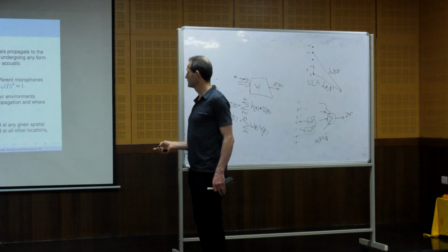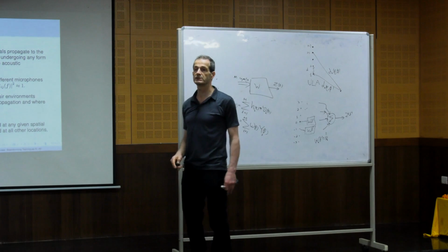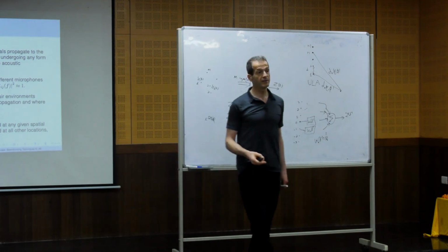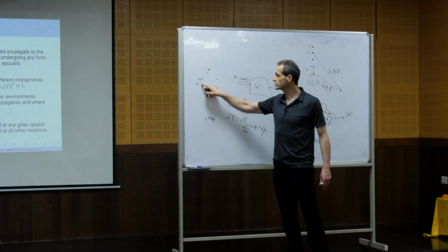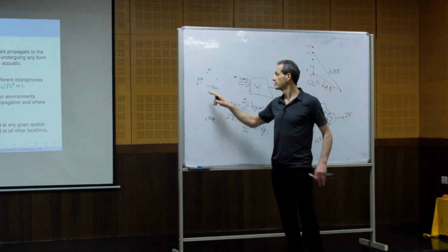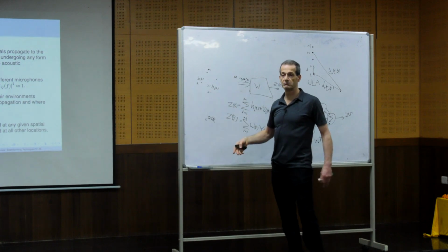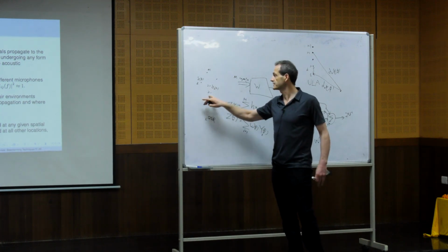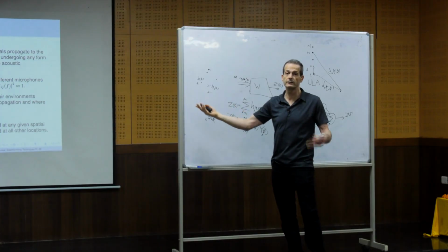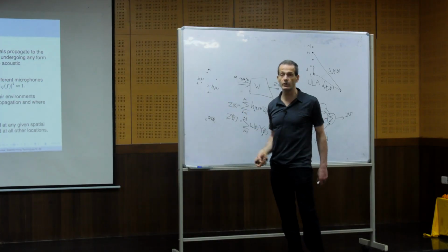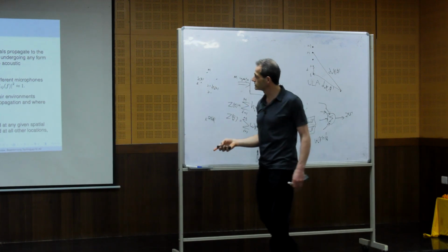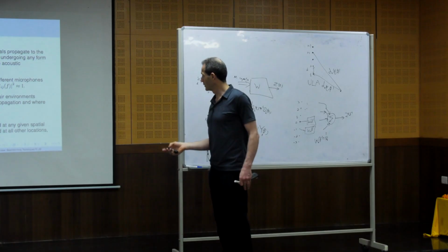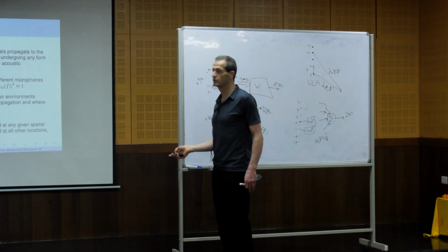In an incoherent noise field, the magnitude squared coherence is close to 0 or even 0. This is true for thermal noise. If each sensor has different noise, maybe even at the same level, but statistically independent or incoherent, the coherence between them is 0 because thermal noise is independent, so the magnitude squared coherence will be 0.